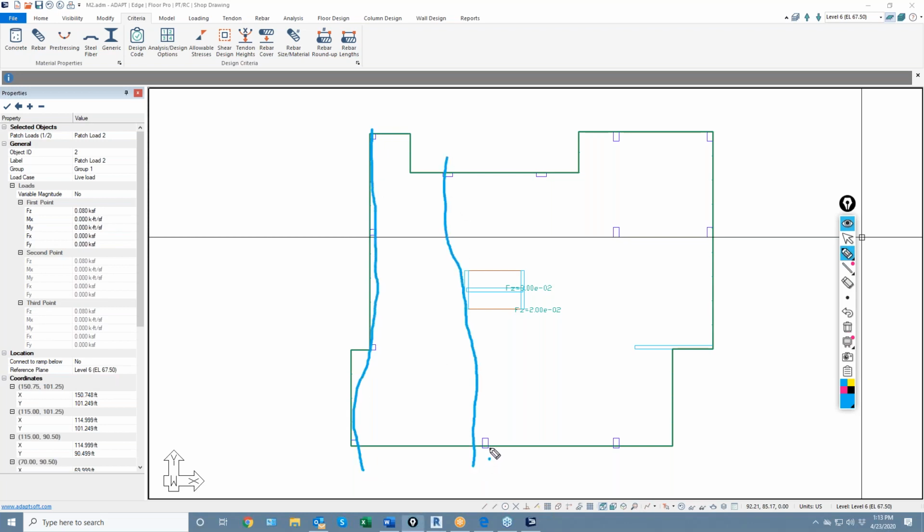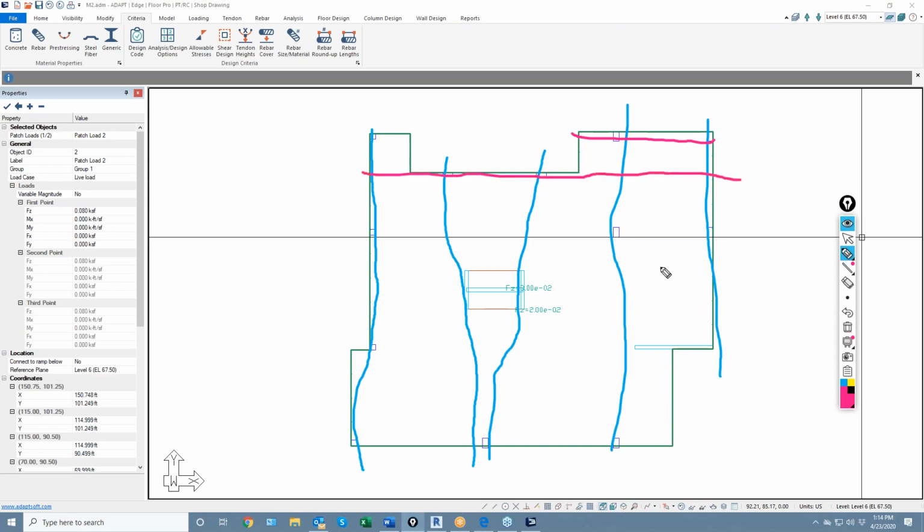This tendon, I'm going to say, will just split. We'll have a tendon here and a banded tendon here. And then I'll represent the distributed tendons in pink. Now, again, if I wanted to represent the distributed tendons as, let's say, bands, then I might say, okay, there's a bundle here. There's going to be a bundle along here. Remember, the blue tendons are banded, so they're really like virtual beams in the slab that carry the distributed tendons. I might have another distributed cable here.